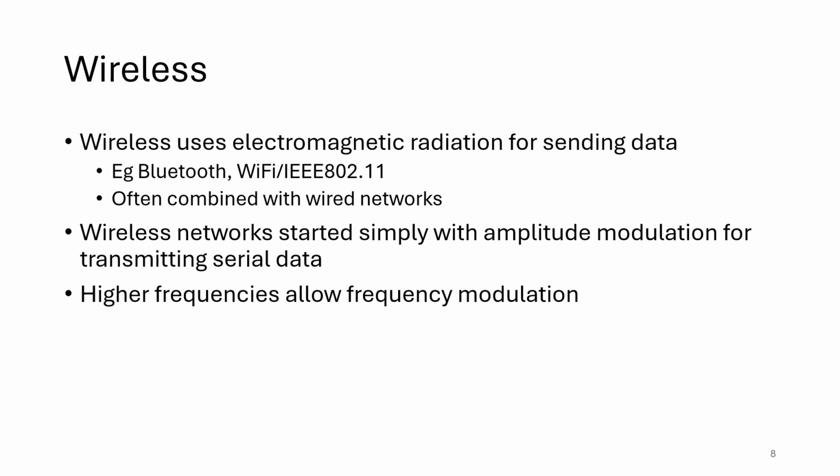and to allow multiple devices to communicate together. Additionally, with the frequencies we're using, typically that would be 2.4 gigahertz, but these days we can also use 5 or even 6 gigahertz. The higher the frequency, the lower the distance, but the more data we can send. And by combining multiple frequencies, we can now have almost as much throughput with a wireless network as we would with a wired network.